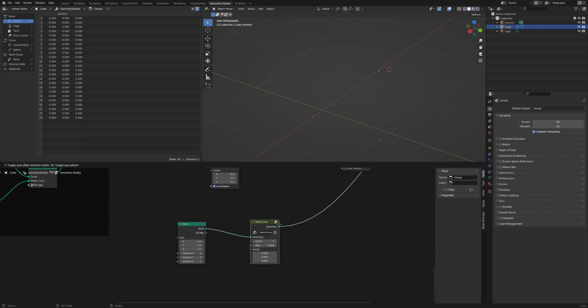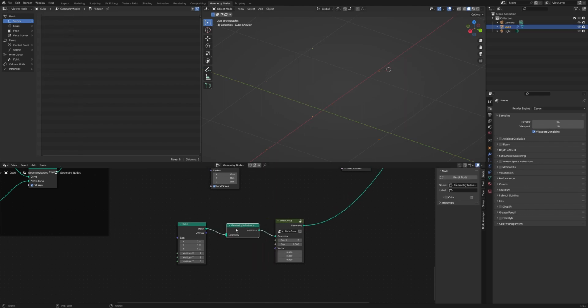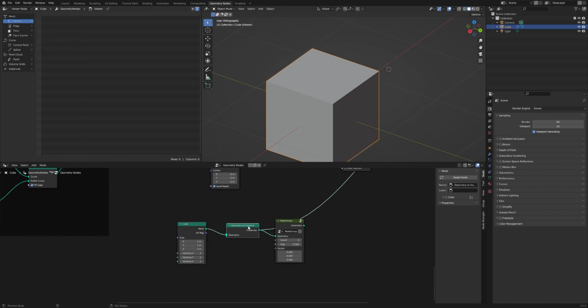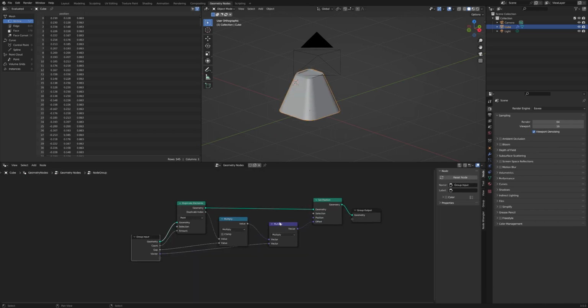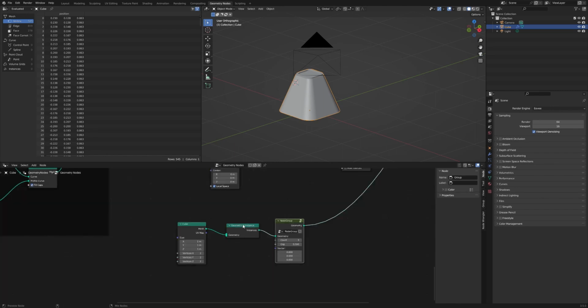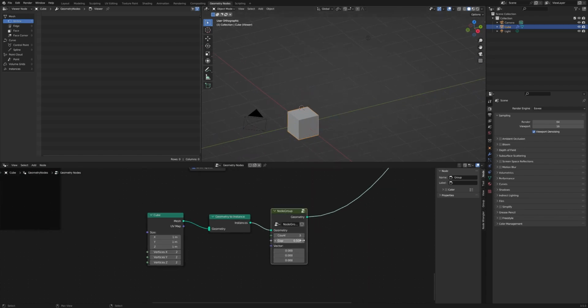Although, remember again, we're going to need to put a geometry to instance on this, because this is duplicating a whole instance rather than just that. Although that is just duplicating the vertices, which suggests to me, yep, there it is, duplicate elements. That should actually be instance, and so then at that point it now will duplicate, depending on the count, the gap.